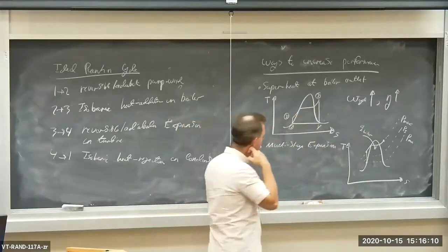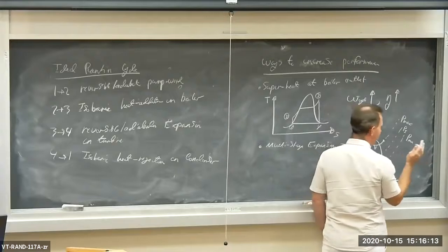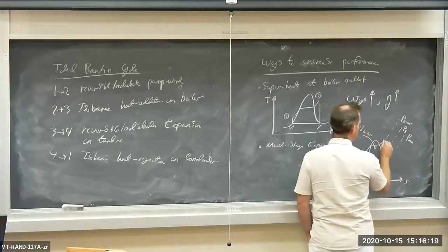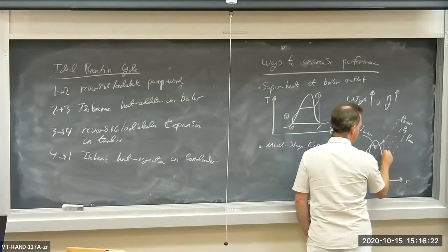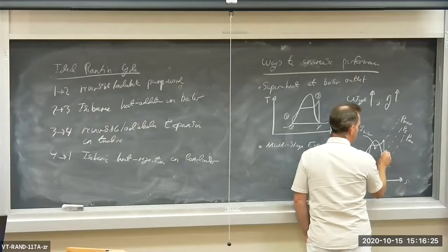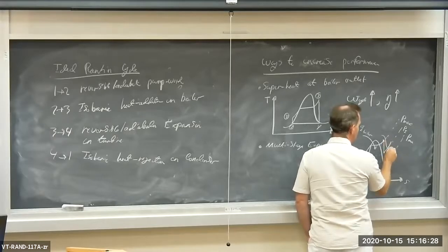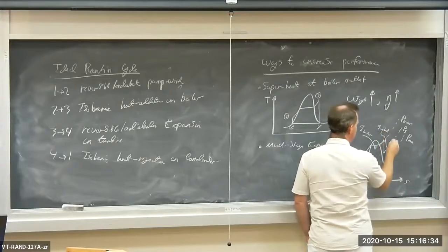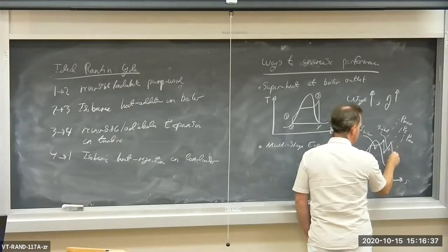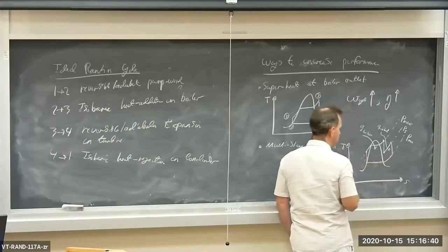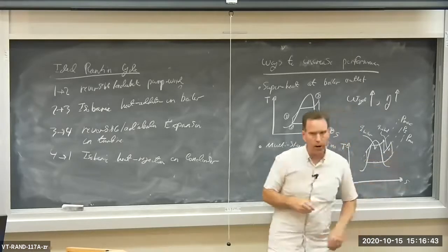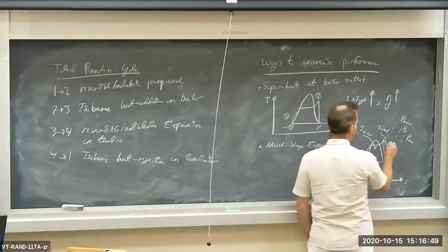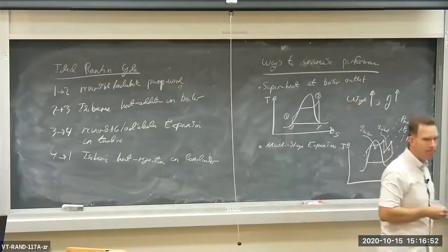And then we can pass the H2O through a high pressure turbine, followed by a reheater, followed by a low pressure turbine. So we have expansion in the high pressure turbine. Then we have reheat. So we have Q reheat. And then we have further expansion. Maybe my diagram isn't the best here. I don't think we're going to end up quite as far out in the superheated vapor region here. But we can have multi-stage expansion in multiple turbines.